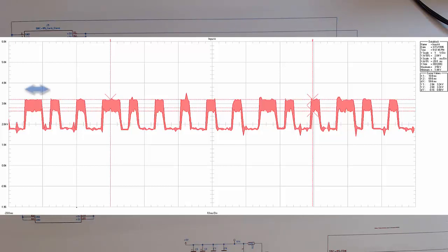So here we can easily see that this is a logic 1 because it's 2/3 high. This is a logic 0. That's a logic 0, another logic 1, 0, 0, 0, 0, 0, logic 1. So it's easy to see just by looking at these whether they're logic 1s or 0s, because we only have to be able to differentiate between 2/3 high and 2/3 low. So it's even easy to do this by eye, let alone with the microprocessor.